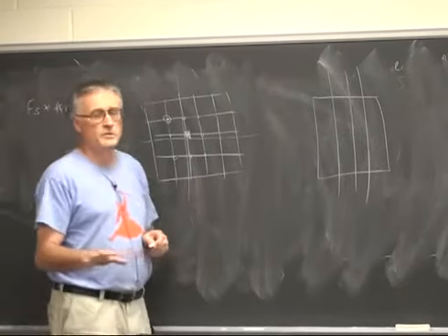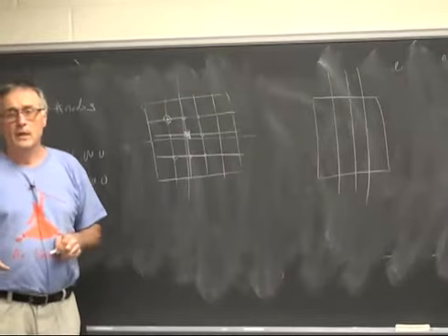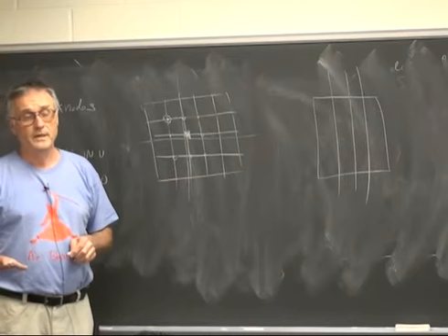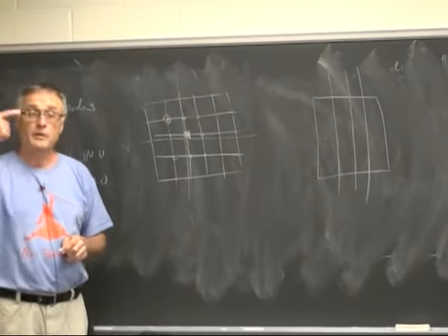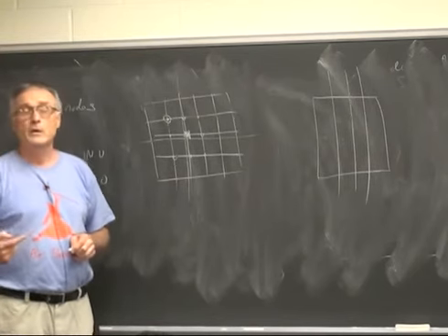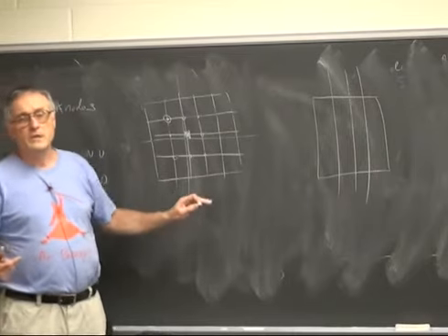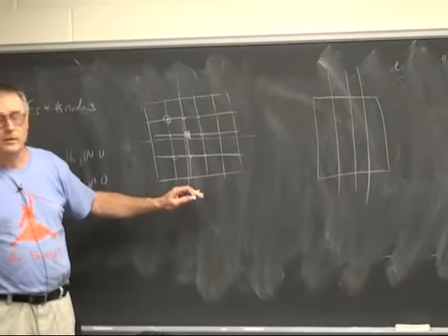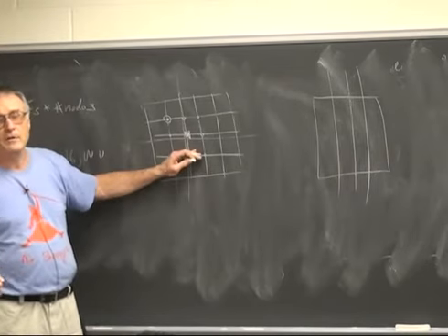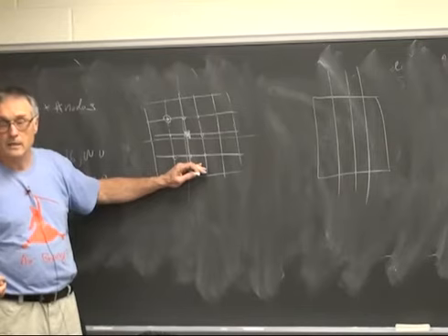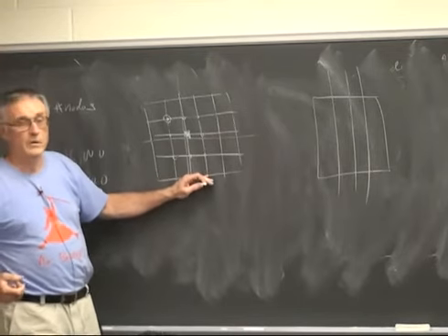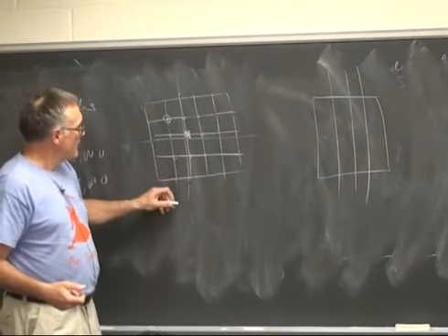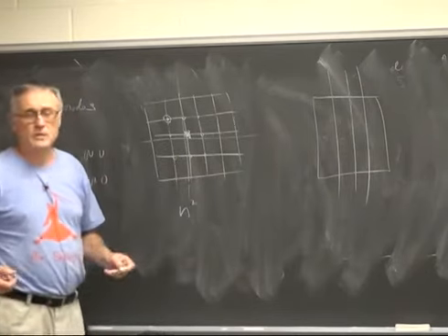There's no conditionals here, no branching, and no loops at all except to compute and compute and compute the same thing over and over. So all of the state machines will stay in phase. They all execute the same code. You can clock them all off the same clock, and they will all stay in phase. So you could build n² state machines.